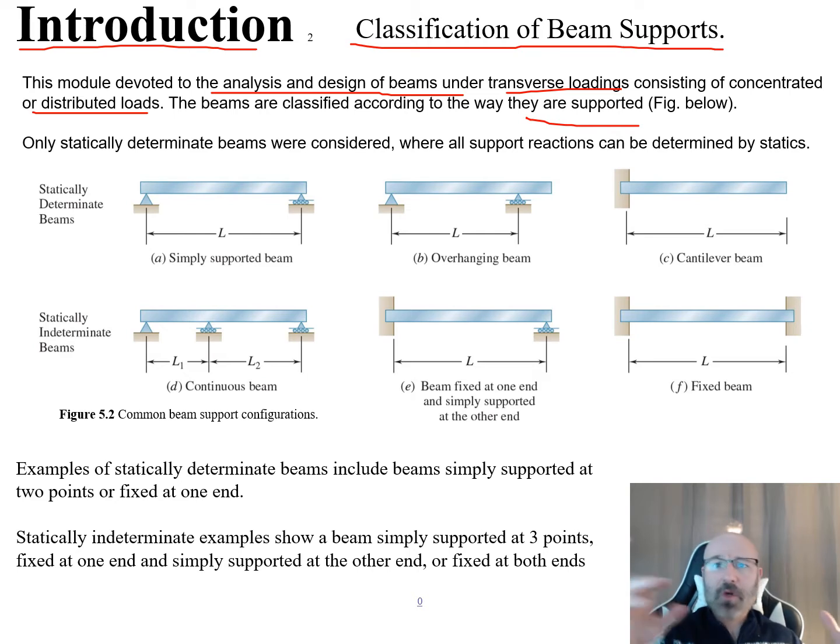And when it's something that's worded in a problem statement, they say, okay, it's a simply supported beam. What does that mean? It's an overhanging beam. It's a cantilever beam. All these different things. We really want to be able to clearly understand when it says that, we know exactly what to draw out. Because as we've seen, not every single problem we're working with, whether it's a realistic problem at your job, a design project, or a textbook problem or an example problem in your textbook, they don't always give you the figure showing what it is.